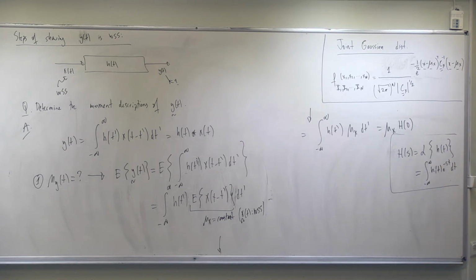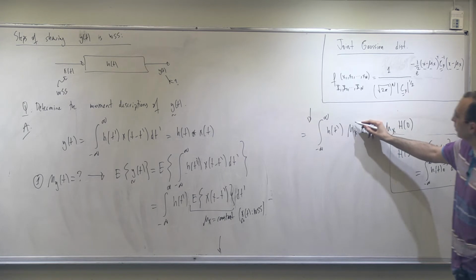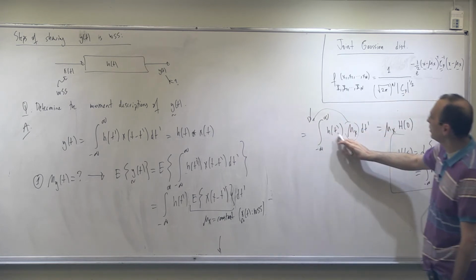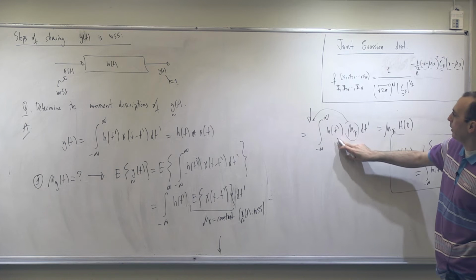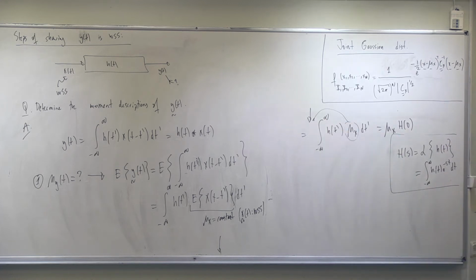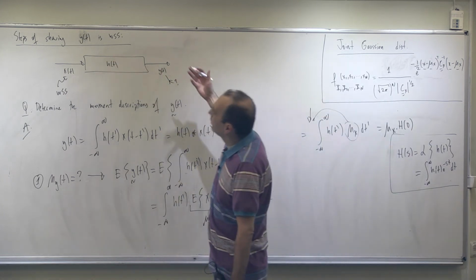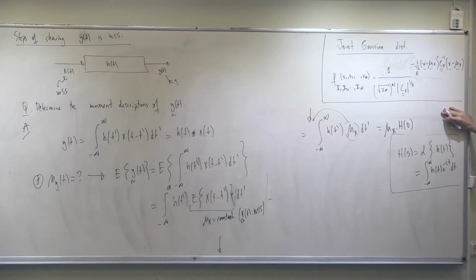So this is just a number. That's my point. This is the area. Take this out of integration. So this is the area under the impulse response, from minus infinity to infinity, and this is just a number, whatever it is. Of course, if it is not infinity, I'll be very happy. If it is infinity, then this is an unstable filter, obviously. I don't care about unstable filters because this is a very practical problem, and our focus is the stable processing. I would like to do some operations on this signal. So you see, this is constant.